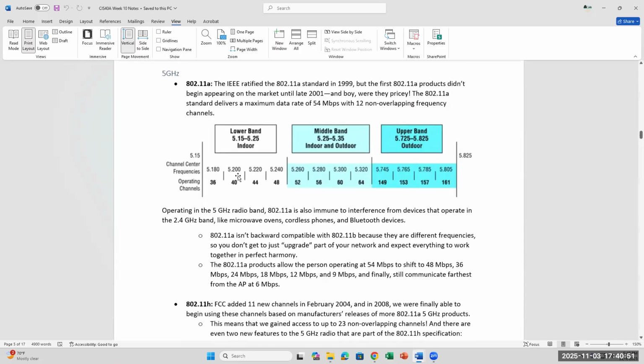The radio band, you want to make sure that there's the least interference. I don't want to say no interference because there's no such thing, right? You know that there's interference in the signal, in how the system would send across. So sometimes you might have microwaves that have high signal, and that can also deteriorate your wireless signal, along with other things like cordless phones that operate at about 900 megahertz. So if you have the lower band type system, and then Bluetooth devices too. Okay.